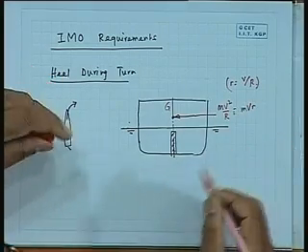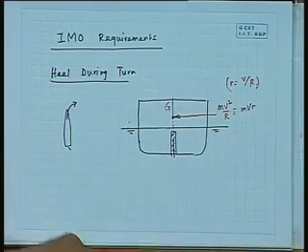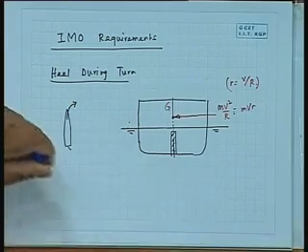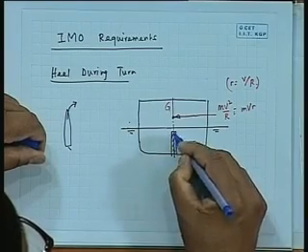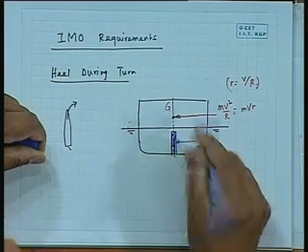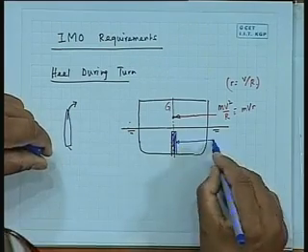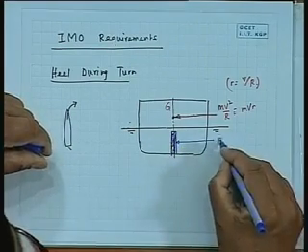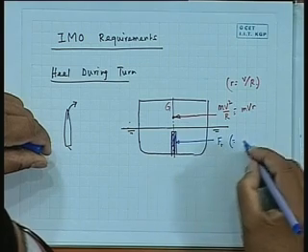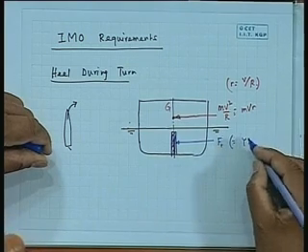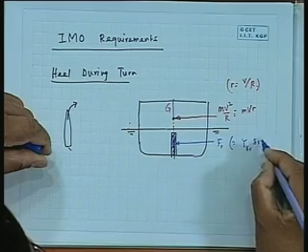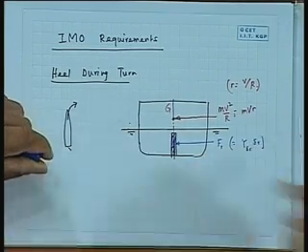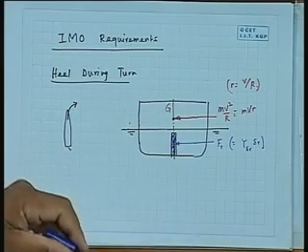Okay. Now we have also the rudder force that comes here. This is my rudder. Typically the rudder will be of this type. So the rudder force comes here, acting F rudder, which will turn out to be equal to Y delta r into delta r. This is the Y force that comes. Essentially that is what you say by definition.